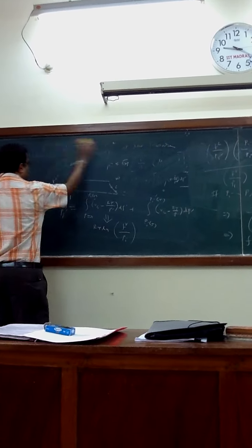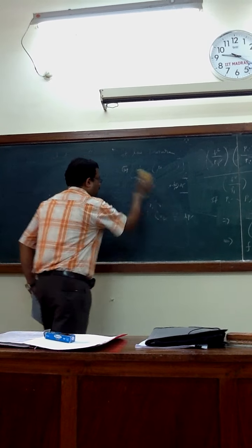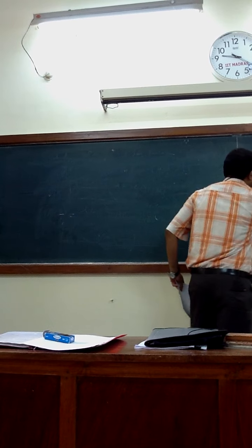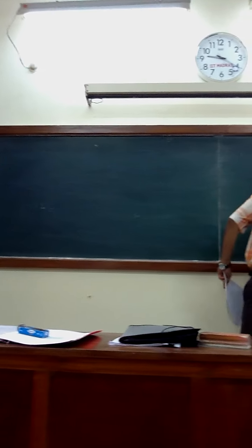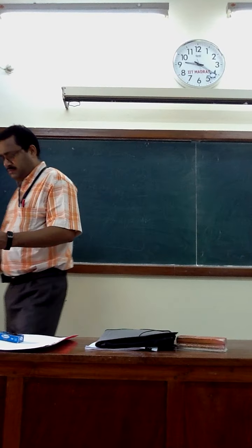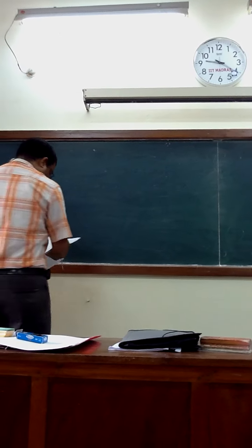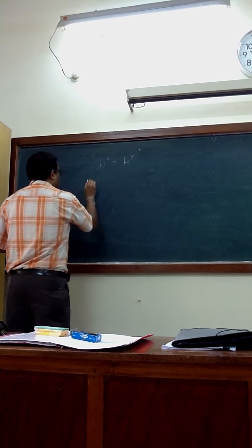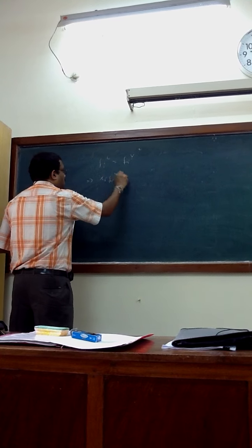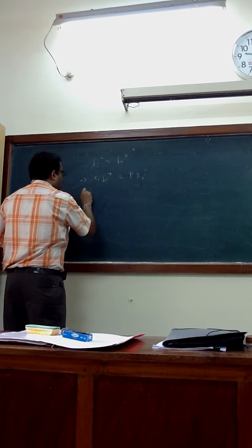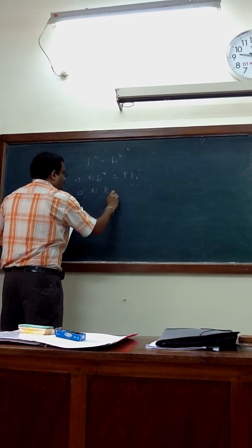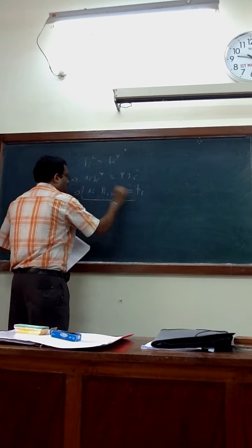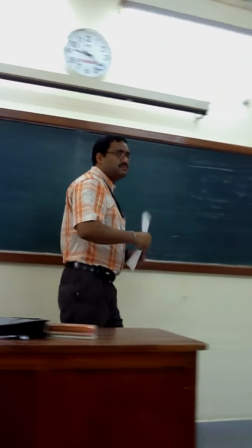what you get from the vapor liquid equilibrium at low pressure is: FIL equals FIV, which is Xi Fi star, which is Pyi equals Xi Pi sat, equal to the partial pressure of the ith component, and that is Raoult's law.